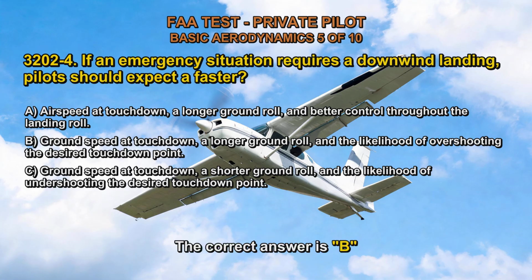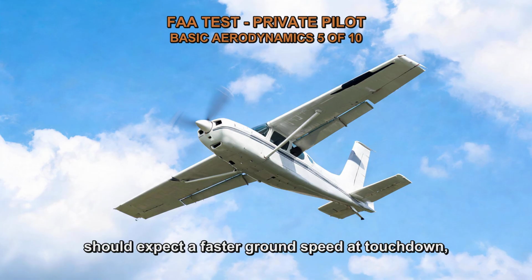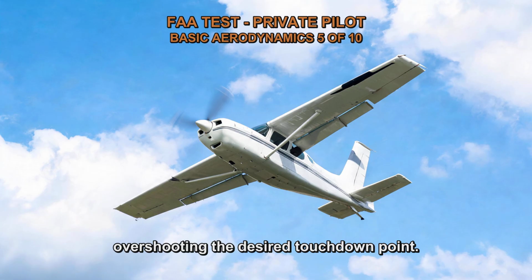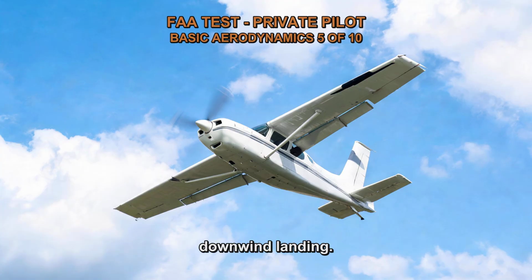The correct answer is B. If an emergency requires a downwind landing, pilots should expect a faster ground speed at touchdown, a longer ground roll, and the likelihood of overshooting the desired touchdown point. Option B correctly describes the effects of a downwind landing.